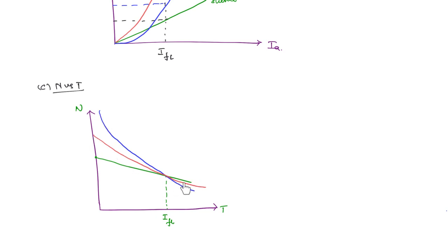So it has the combined advantages of both. Like a series motor, it can offer a high starting torque, which becomes important in certain applications. And like a shunt motor, it will not overspeed. Okay. So this green one, you can write it as the shunt motor, and the red characteristic is the cumulative compound motor. And finally, you have the blue characteristic series motor.